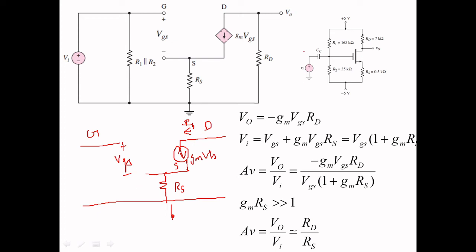So you can see now, I am repeating again. In the source you have a source resistor, and between gate and source you have a drop VGS, that is the input voltage. Then the output current is GM times of VGS. Other than that, you remove this supply, so R1 and R2 will become parallel. Then remove this supply, this RD will come to the ground, then V0 is returned, the capacitor will become short circuited, and VA you are getting here. So this is your final thing.